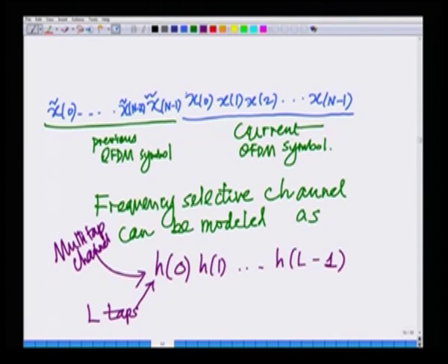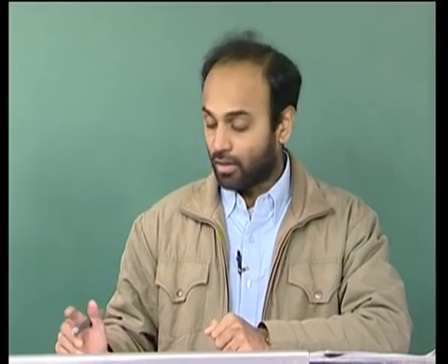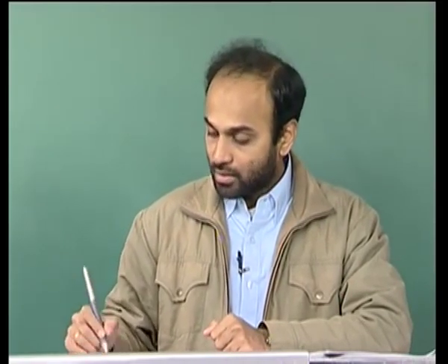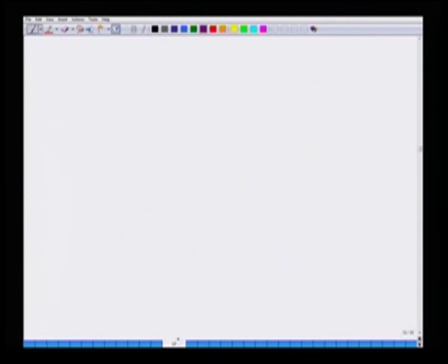I am transmitting my OFDM symbol block across this frequency selective channel, and I want to see what kind of signal is arriving at the receiver and whether there is any problem with it. So, now I pass these two OFDM symbols, in fact big OFDM symbols of duration n over B, through this multipath channel. Let us look at the first symbol that is received.